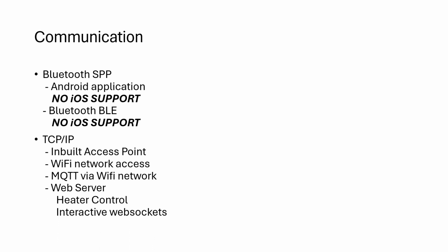Under the TCP IP, you have a built-in AP or access point within the Afterburner that has a static IP address, broadcasts its SSID out like a standard wireless network. You can always connect to that, and that AP can be custom configured so you can prevent others from getting into your system if it was an issue.